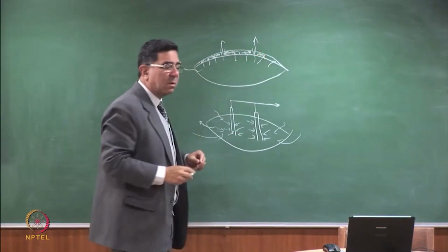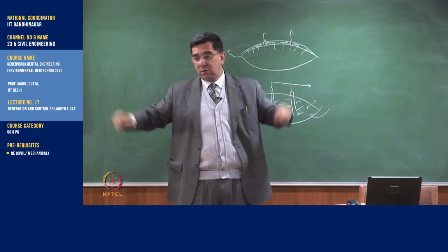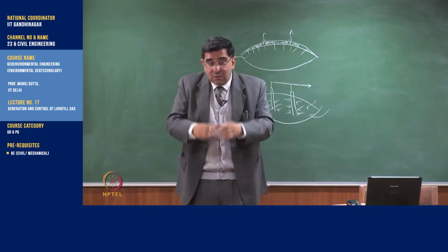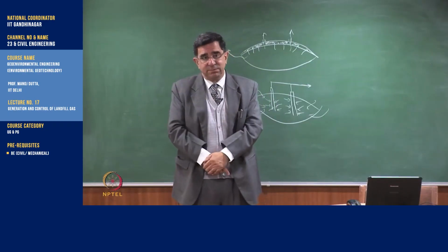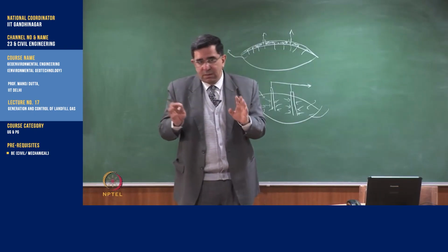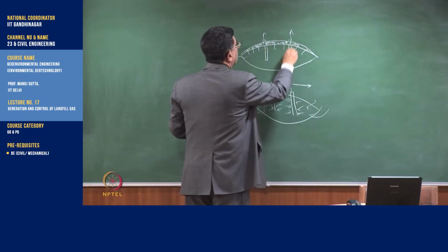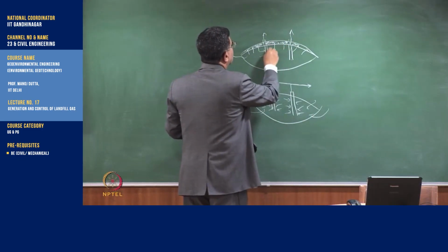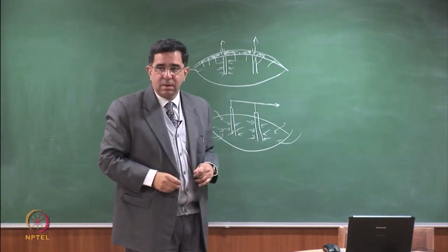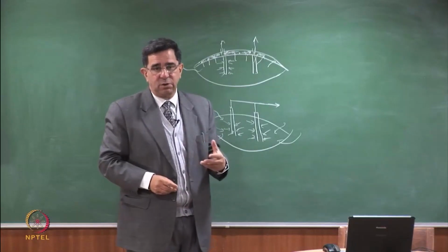So a good passive system is one which has a gravel blanket at the top. You want even a better passive system, you can make the wells and fill them up with gravel. But you're not applying any suction, so it's still passive. Then under self pressure, it goes to a closer drainage path. The moment you start extracting, that's the time you've got into an active system.